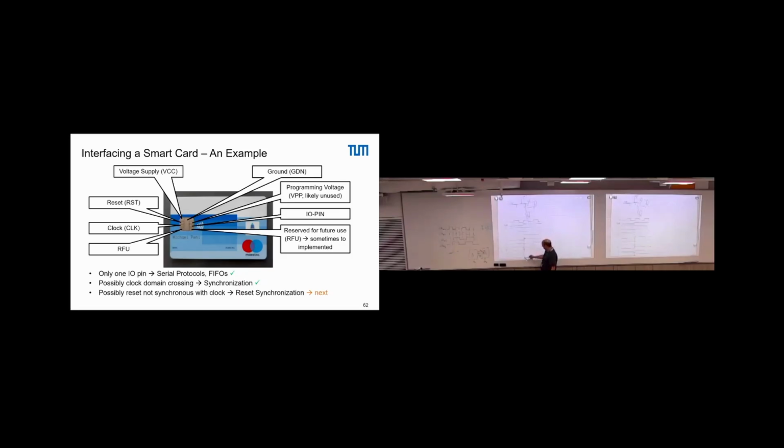So you see this grayish line, which corresponds here to this rising edge. And we are a tiny little bit behind. That is sufficient that our flip-flop stays in reset and stays 0 here. Okay? So what is the problem now? Our system here starts with a state to process where one register is already set, the other two are not set. Also, we wanted to start the system from a state where everything is set.